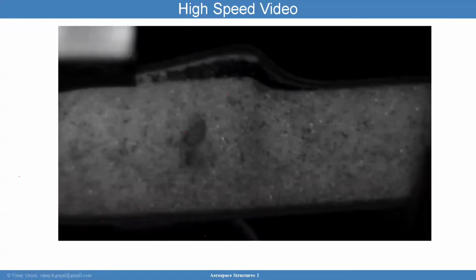What you can see here is the initial failure, where you see that failure is happening on the adhesive. For these 3-point bend specimens, we really designed them to fail in shear. I know there's at least one video that shows that, so we probably had enough evidence in this case. There was a good failure. You could see how it grew shear wise, and it's like, okay, we have good evidence. We know how this happens. We also know how fast it happens, right?